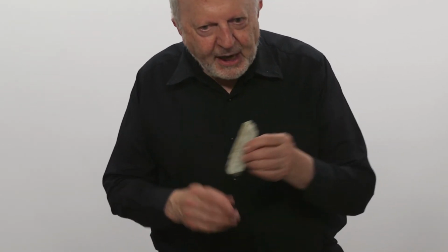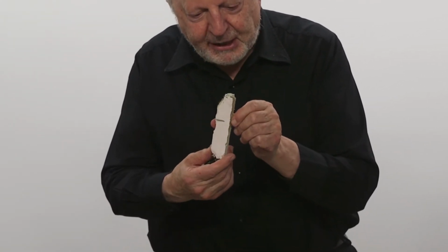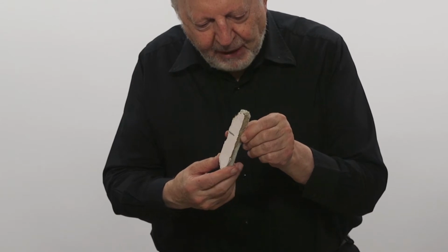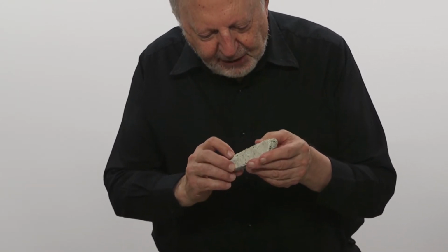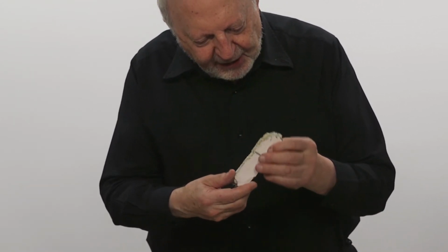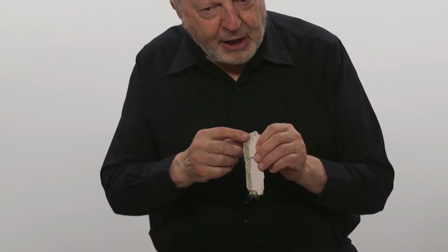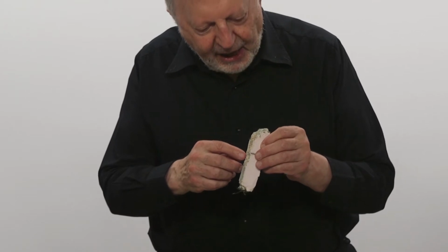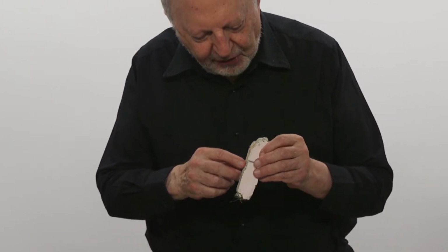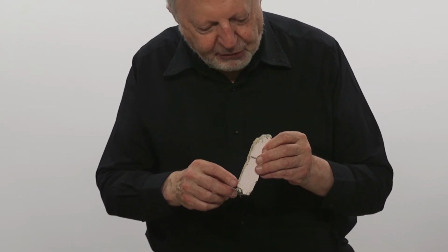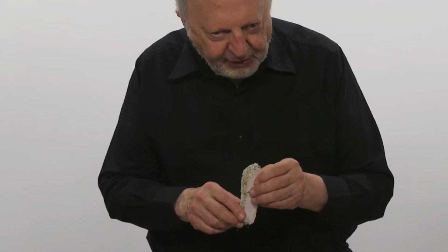This here, for example, is a cement render. There's the face of the building has this pink paint on it. Behind it is a sort of layer of cement and possibly plaster, and it contains within it hairs. Commonly on the face of a building, and in fact on internal plastering as well, you would add either animal hair, like horsehair and so on, or occasionally some other material like straw into the plaster to reinforce it.